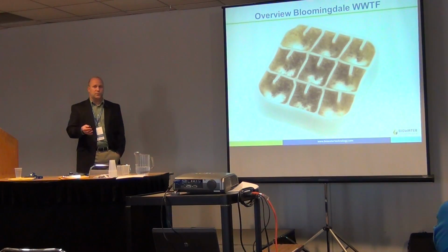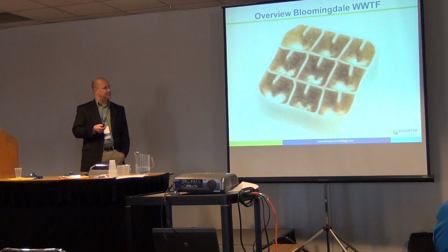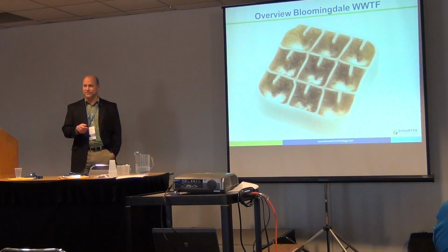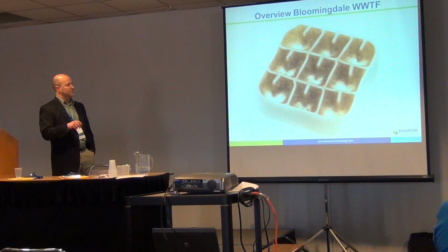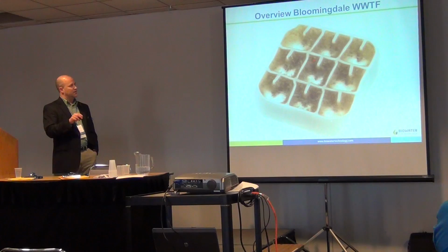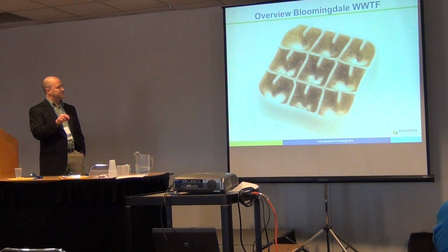So the whole crux of a fixed film system, and when I say fixed film, I'm talking about IFAS and MBBR, moving media in a tank. Other similar fixed film systems are trickling filters as well as RBCs. What we're going to focus on is a floating media-based system, where this is the internal surface area. So when we talked about the 900,000 square feet of surface area required, that's all in here.